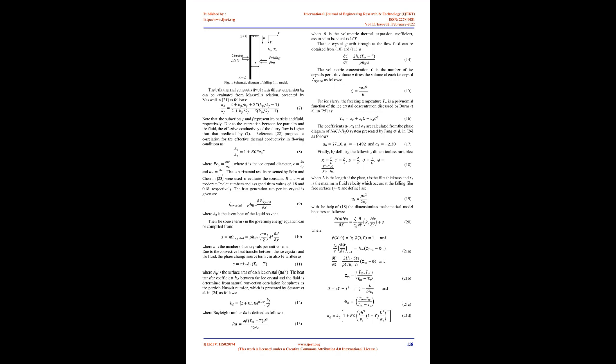And the effective kinematic viscosity is defined as follows. (4) The effective specific heat of the slurries is the averaged mass specific heats of the fluid and ice particles, which is defined by Stewart and Stickler [20] as follows. (5) c = C c_P + (1 - C) c_F, where c_P and c_F are the specific heats of the ice particles and fluid, respectively.